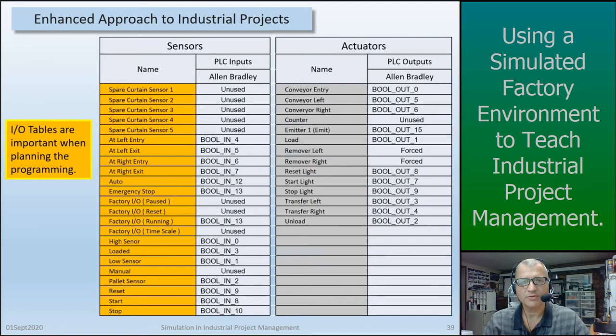The other nice thing about using the simulation is I can create an I/O table, which is also important when planning and programming. Because I have everything in the simulation set up correctly, I can automatically generate an I/O table from that. So that's just kind of an aside there.